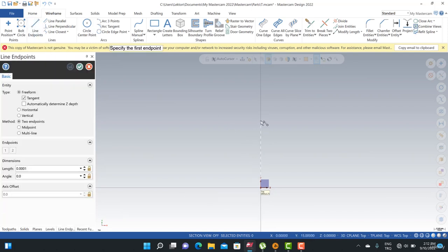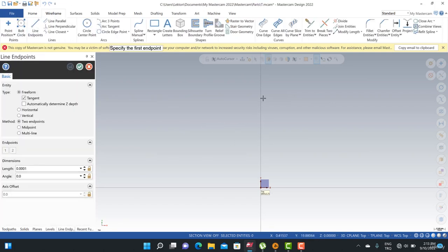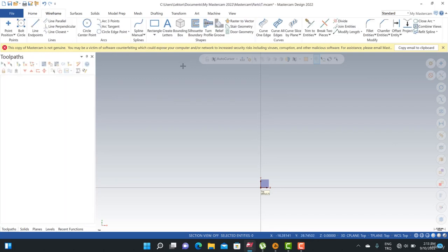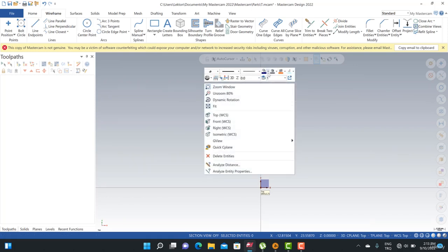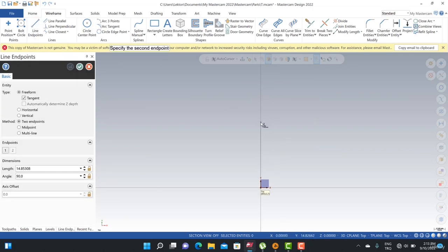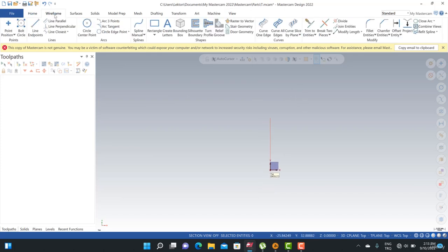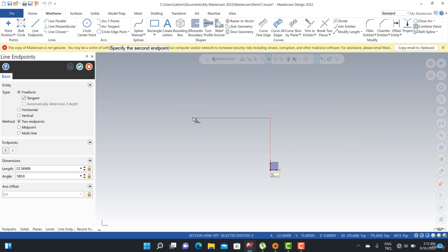And then I can also create another line here. Okay, I can delete it, sorry. I can create my line with endpoints here. You know that it's quite difficult to see your line, so let's turn back to here and make that red, and then we can create our line like this, and then I can write my distance. Okay, we can also turn back to view and make that part unselected, and then we can see our wireframe.